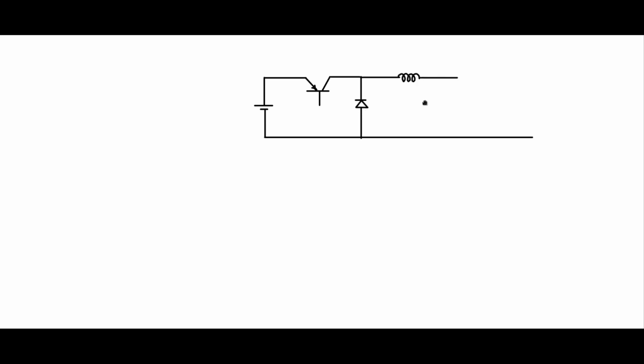Let us see if we can apply them to our DC-DC converters. Now let us take the simple non-isolated buck converter. It is something like this. Now here on the rail side, on the positive side, let me put a PNP transistor like this. If you are doing it on the ground side, you can use an NPN transistor. So let me put this PNP transistor and let me complete this buck converter circuit by putting this diode, inductor, capacitance, resistance, and then you are taking the output across these two terminals. This is VI and this is V0, measured in these two fashions.